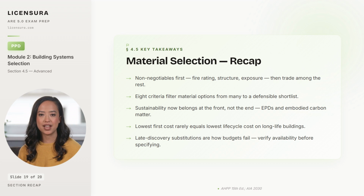The 8 criteria, structural, fire, durability, moisture, sustainability, aesthetics, cost, and availability, filter the universe of available materials down to a short list the team can actually choose among. Sustainability has moved from an end-of-process check to an early filter as embodied carbon targets become contractual. Specify EPD-backed materials early, or you'll redesign for the carbon cap later.